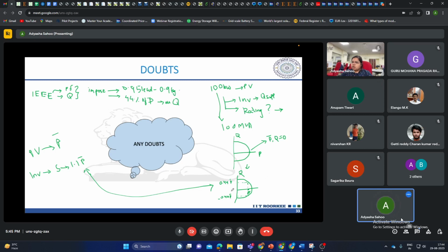But generators are operating at 0.8 lag, right, ma'am? Not always. They get a range within which they have to maintain, and not always lag. They can also be requested for lead operation, but it is very little. You can see 0.95 lead only they're expected. So this is for DRs, and generators are from 0.9 lead to 0.9 lag, I think.